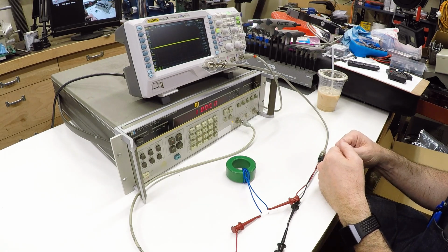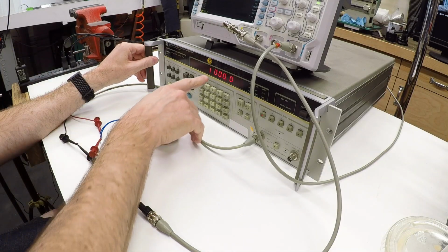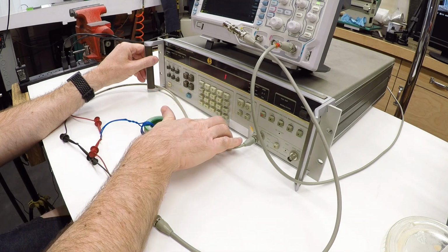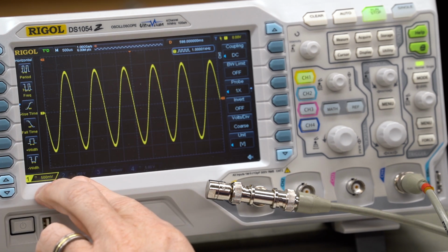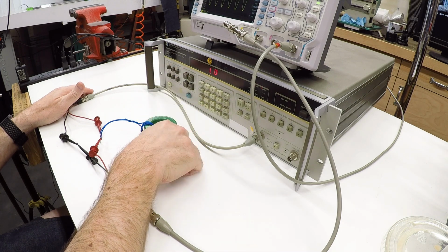And once again, this is an ancient piece of equipment. The fan generates quite a bit of noise. So let's start out with a 1 kilohertz sine wave at 1 volt RMS. And we've got that here on the oscilloscope, and you can just see the sine wave. Now, last time we went through and we ran this through a whole bunch of different frequencies manually and looked at the output response. But I want to set up the frequency sweep to do that instead.